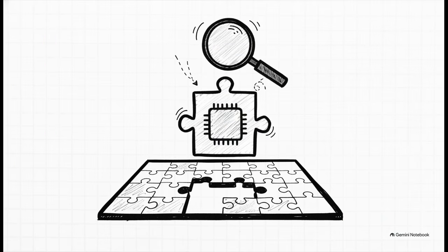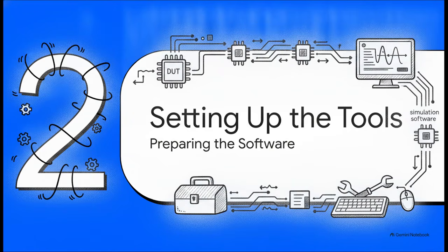Now, you might be wondering about that target design we're testing. We call that the DUT, or Design Under Test. In our explainer today, the main DUT we'll look at first is a multi-bit adder called addern. The DUT is the actual puzzle we're testing inside our virtual lab environment. And what's cool is this test bench module can actually be saved right inside the exact same .v file as the addern design itself.